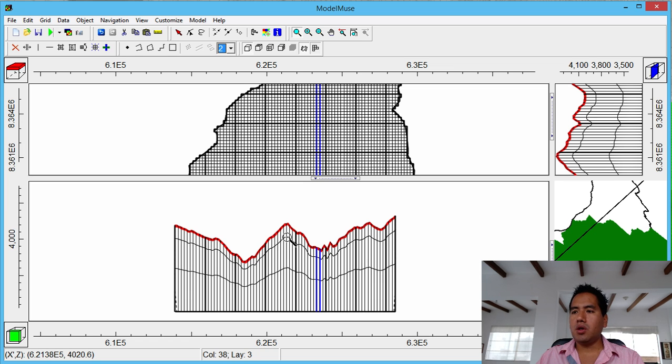What you will know is that hydraulic conductivity depends on the depth. So if you set a single hydraulic conductivity for the whole depth, in a model that has 600-meter depth, you will be introducing some errors in defining the deep groundwater flow. That's why I suggested putting more hydraulic conductivity here, less here, and even less here. Okay, check.